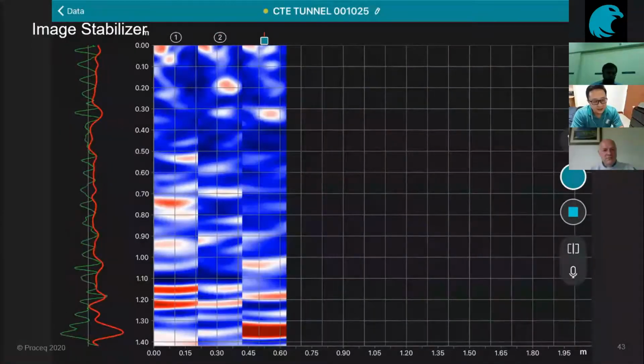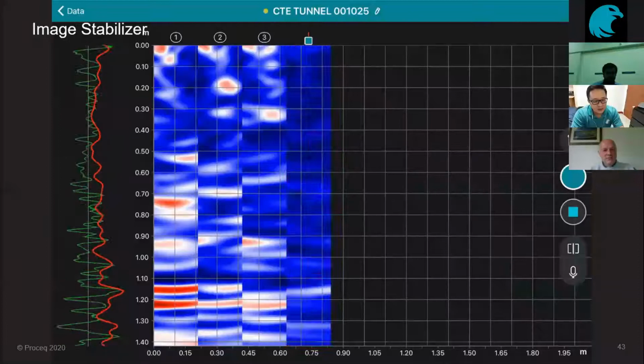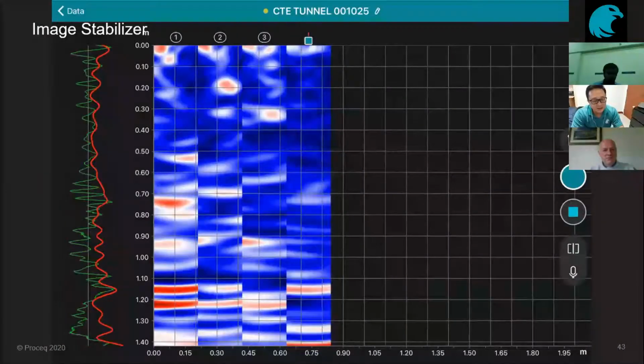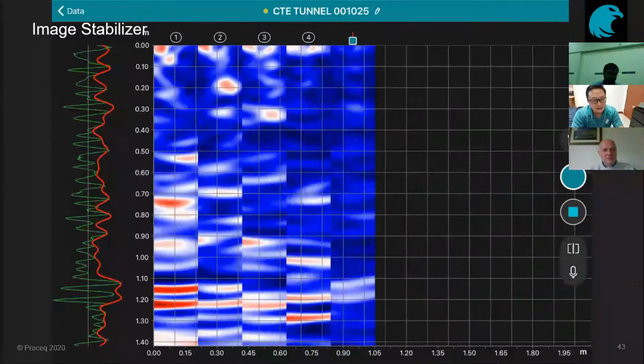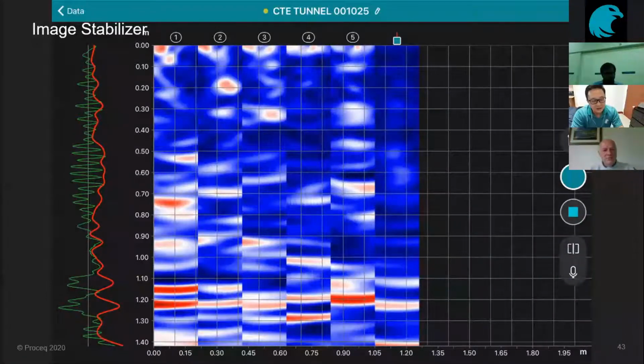You can see the A-scan, which is on your left-hand side, is very unstable. The reason is that the overhead tunnel location is just under the expressway, so many vehicles pass through during our data collection. We know UPE is a kind of direct contact testing, right? It uses a mechanical wave, so any background resonant energy will greatly affect the stability of the real-time B-scan image. So what's the solution? Look at our stabilizer.